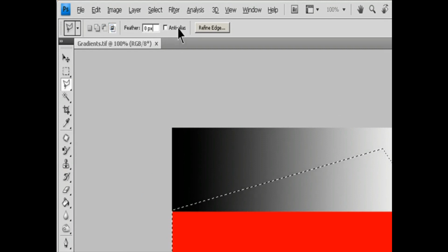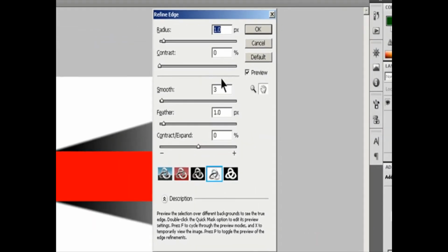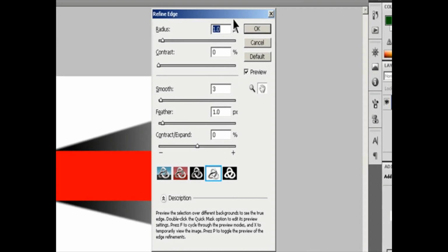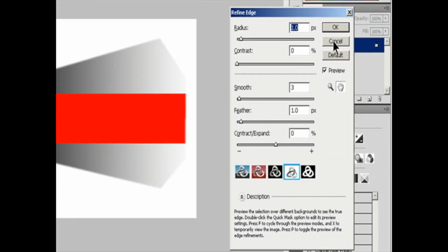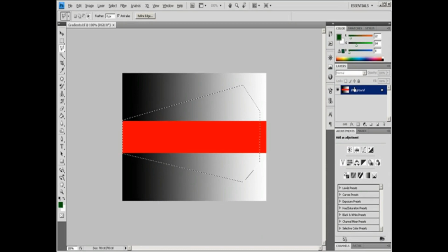5. Do one or more of the following. To draw a straight segment, position the pointer where you want the first straight segment to end and click. Continue clicking to set endpoints for subsequent segments. To draw a straight line at a multiple of 45 degrees, hold down Shift as you move to click the next segment. To draw a freehand segment, hold down Alt in Windows or Option in macOS and drag. When you finish, release Alt or Option and the mouse button. To erase recently drawn segments, press the Delete key.